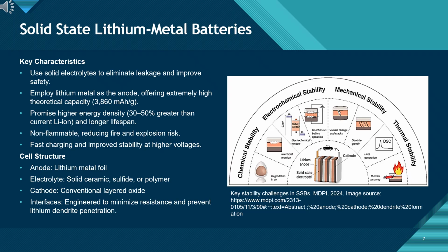Solid-state lithium metal batteries. Now let's talk about solid-state lithium metal batteries, or SSBs, the next big step in battery technology. Unlike today's lithium-ion batteries that use liquid electrolytes, these use solid materials, ceramics, sulfides, or polymers, which means no leakage and far less fire risk. The lithium metal anode gives them extremely high capacity, about 30 to 50% more energy than standard Li-ion cells. That means longer range for EVs or smaller battery packs for the same power.